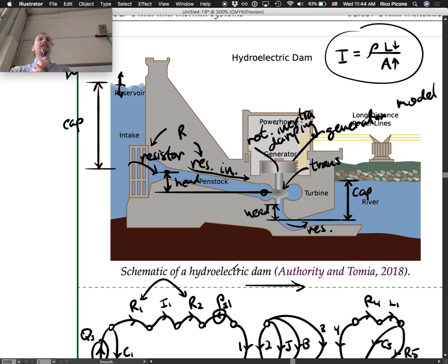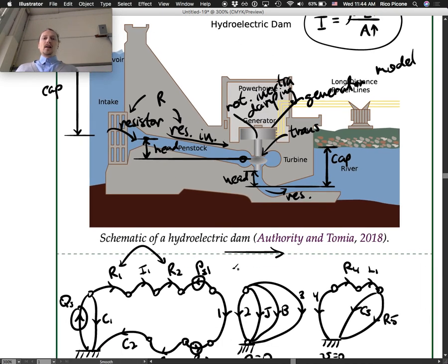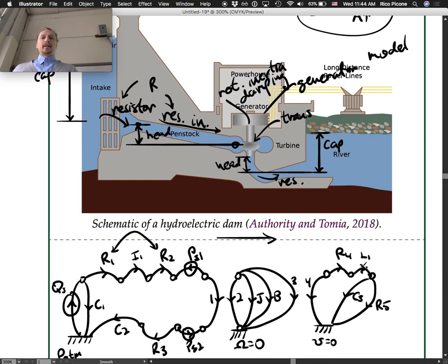And for the electrical side too, so we just have to assume the R4 and the inductance and all that, because there's nothing really modeled up there on the actual picture of that too. Right, so we're just basing this off the knowledge that I said it's a DC generator. So a DC generator is going to look something like this. For an individual generator, we would have to know what its winding resistance is and also its inductance, which are spec sheet things you would be able to find or measure as well.